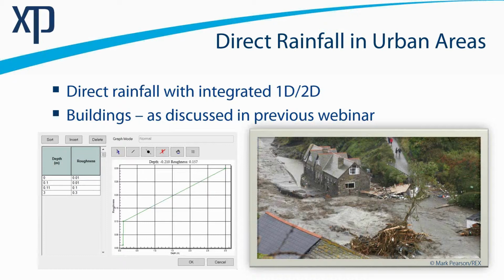So once the water starts to get deep, if you have a building which actually floods, it has water depths greater than say a foot or so, the building essentially becomes a barrier to floodwaters or an obstruction to floodwaters. So what modelers tend to do is for those higher depths, if water does get that high, you're basically saying the building is in a flooded area and it becomes an obstruction. So you increase the Manning's n value quite substantially once you get above 0.1, 0.2 of a metre or around about a foot of water. So it's an interesting approach that's worked quite well in quite a lot of studies in Sydney and elsewhere, and certainly a nice way of modelling that sort of situation.